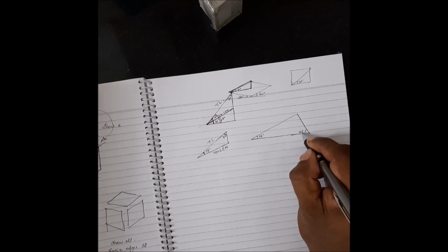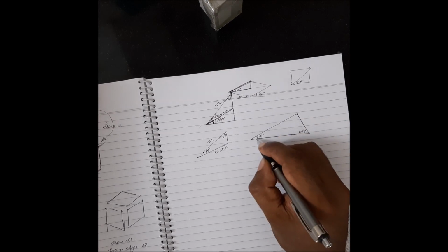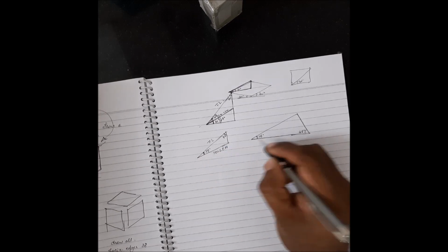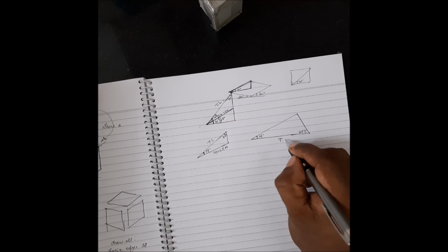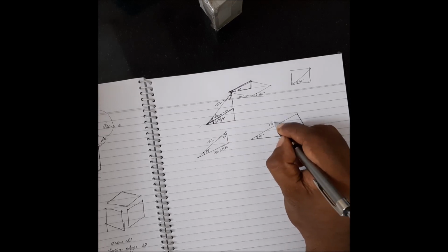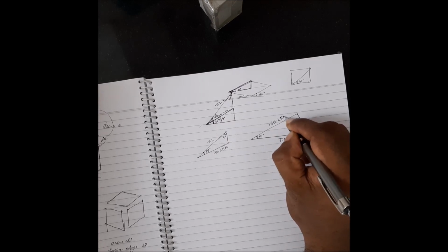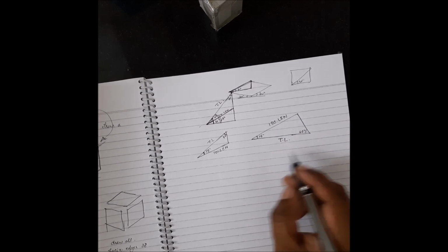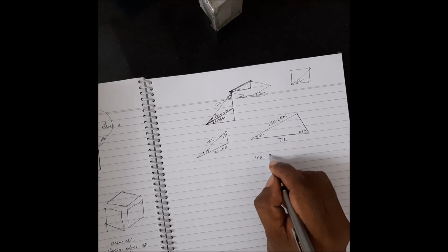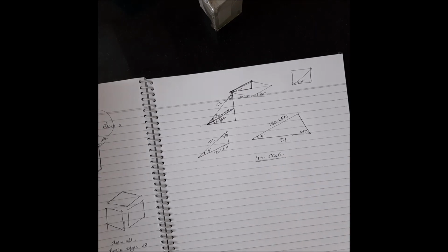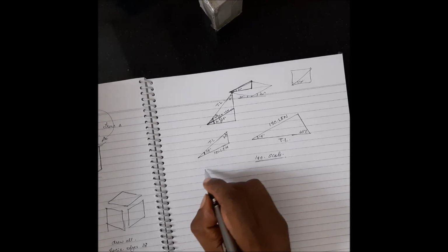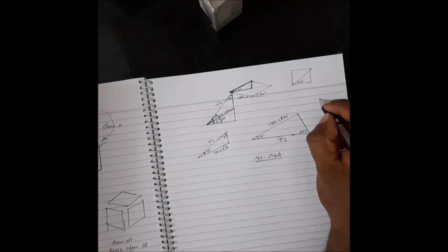So this is 45 degrees, right? So one side 15 degrees, the other side 45 degrees. This side is your true length side and this side is your isometric length side. So right now what you see is called the isometric scale. Now the good thing is, if you know the actual length of the square, let's say it's 30